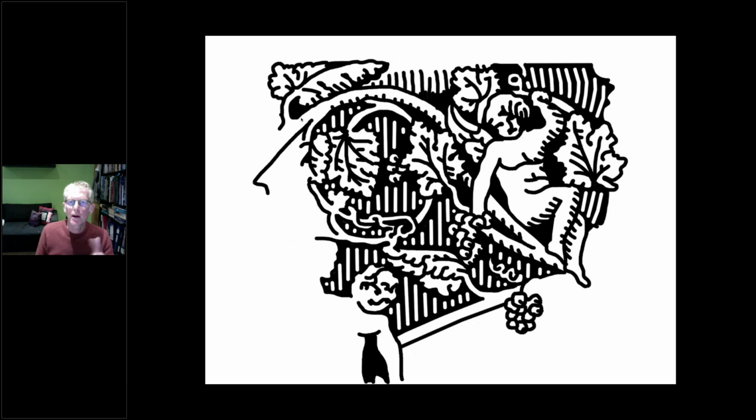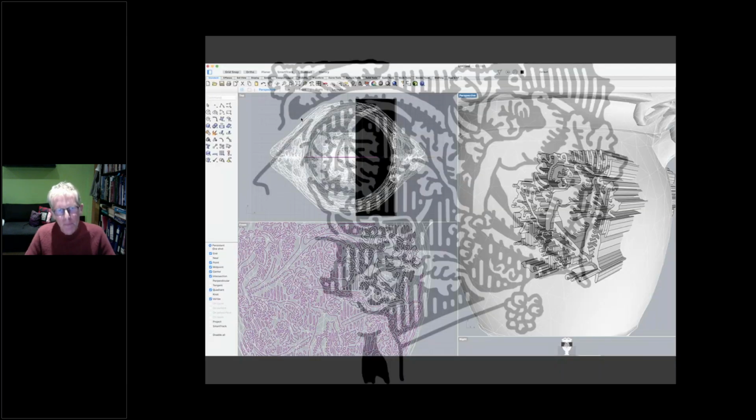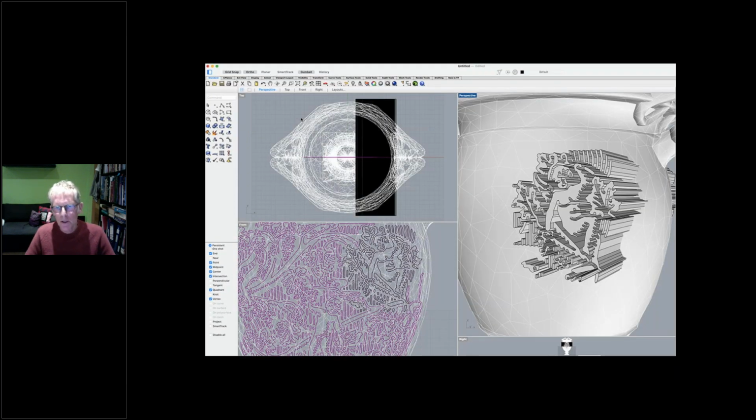So I had to simplify them in the creation of these drawings. That's obviously just a small section of it. And then convert my drawings to curves, which could then be extruded. Which was very time consuming, as I don't know a simple way to import line drawings into Rhino and translate them directly to curves. I'd be very interested to know if there is a way, and dare say that I've probably missed some simple technique. So maybe that's something we could have a chat about afterwards. And if you know how to do this, please let me know.